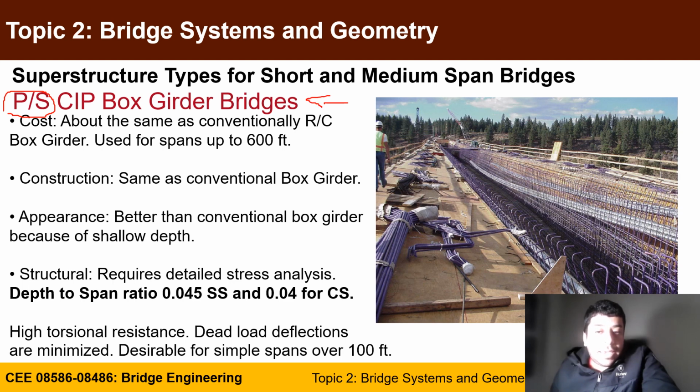In this case, you can see the reinforcement is placed, and those ducts are to create a void after casting, so you can insert pre-stressing strand and post-tension the girder afterward. So you cast first and post-tension second, and release the force to apply those compression forces.